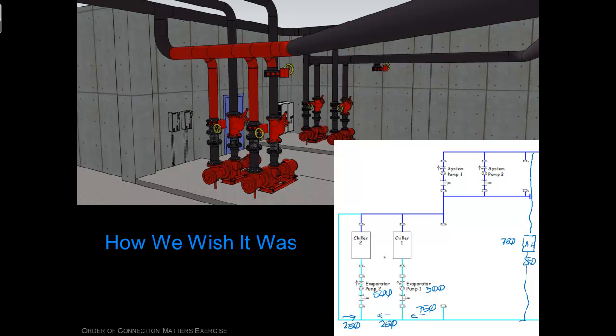In the Midwest, we called the pumps that pumped the distribution system the primary pumps. I think the perspective being that the load's out there, so that's the primary purpose of the system. So they were the primary pumps, and the pumps that pumped the chillers were called the secondary pumps. On the West Coast, most people call the pumps that pump the chillers the primary pumps, and the pumps that pump the loads the secondary pumps.